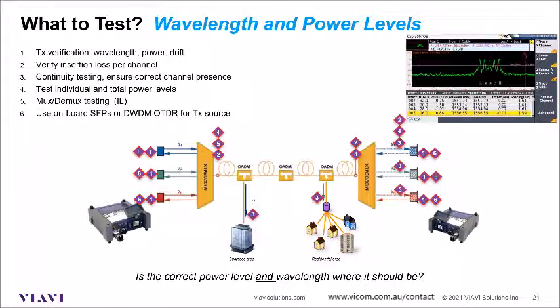There is also the verification, as you would for fiber qualification, of the insertion loss. Here we have to talk about the insertion loss per channel, so there could be a different insertion loss for the different channel wavelengths as well. It's important that this is done properly using the right tools, because the real fact is that these channels have different endpoints in the network architecture. They have a common path in the middle, but on the fringes they could all end up with different lengths and different network events, like splices or connectors or what have you. So the insertion loss per channel is very important here.